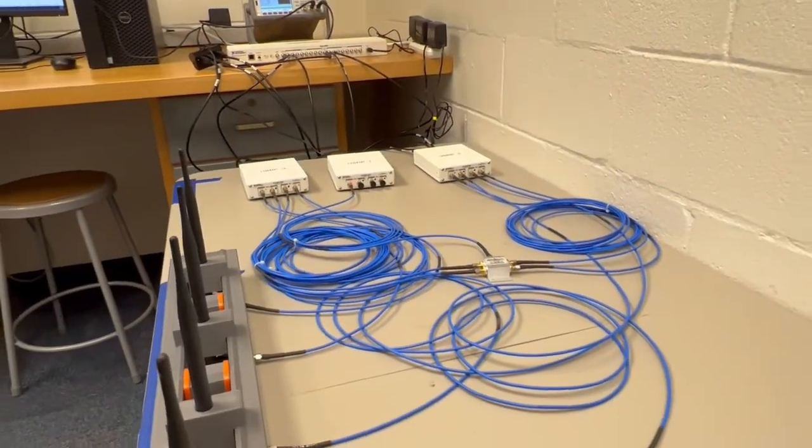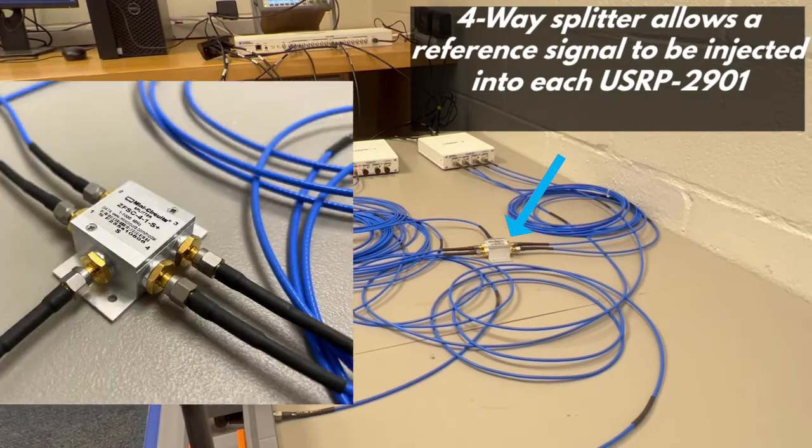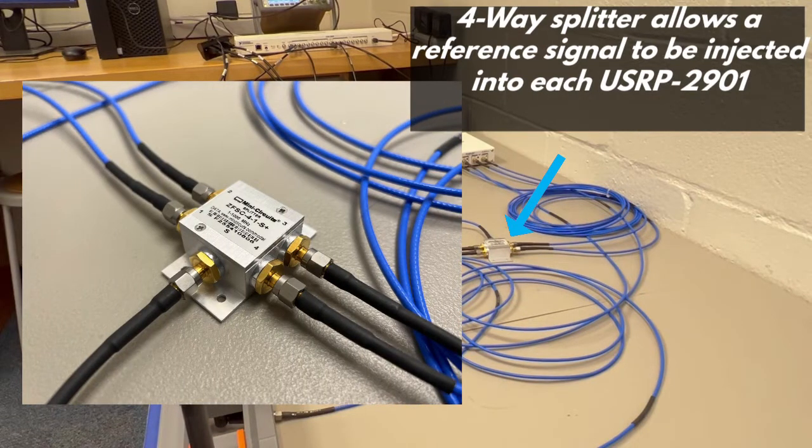Located directly behind the ULA is a 4-way splitter. The 4-way splitter allows a reference signal to be injected into each USRP and therefore allows us to calculate a phase offset between each received signal.